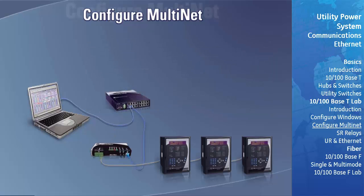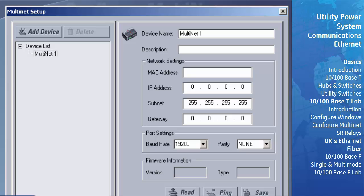To configure the multinet, launch its setup software, which can be found on the GE Multilin product CD or website. Enter the MAC address found on the multinet label, in addition to a unique IP address. We will enter an IP within the range of our test network addresses. Next, enter the subnet mask. Here we will enter our test network address. The gateway address would only be added if one existed.